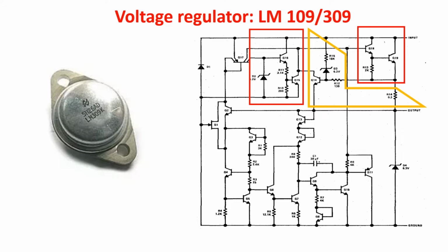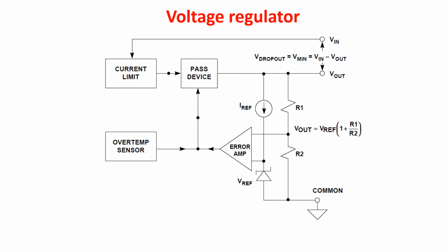Additionally, a 5-volt regulator works with a relatively low voltage across the integrated circuit. Because of the low voltage, the internal circuitry can be operated at comparatively high currents without causing excessive dissipation. Both the low voltage and the larger internal currents permit higher junction temperatures. This can also reduce the heat sinking required, especially for commercial temperature range parts. Now let's see the general block diagram of the regulator. We have three terminals: the unregulated input, ground, and the regulated output. We have a voltage reference symbolized by a Zener diode, but we'll see the 109 uses the bandgap reference.